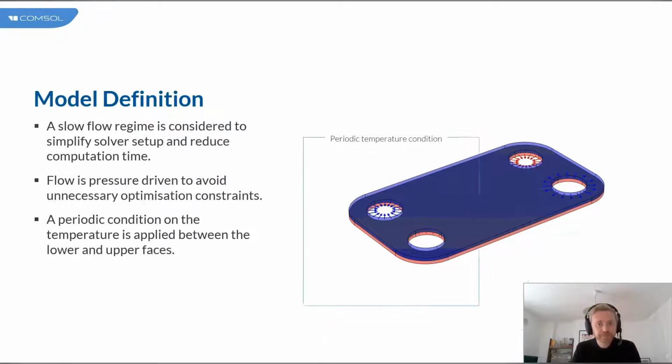Now, because this is intended to simulate a stack of these plates, I will use a periodic condition on the top and bottom, and this is intended to give the effect of this being a repeated stack of these plates in reality, whereas in the model, I'm only looking at just simulating a single plate.